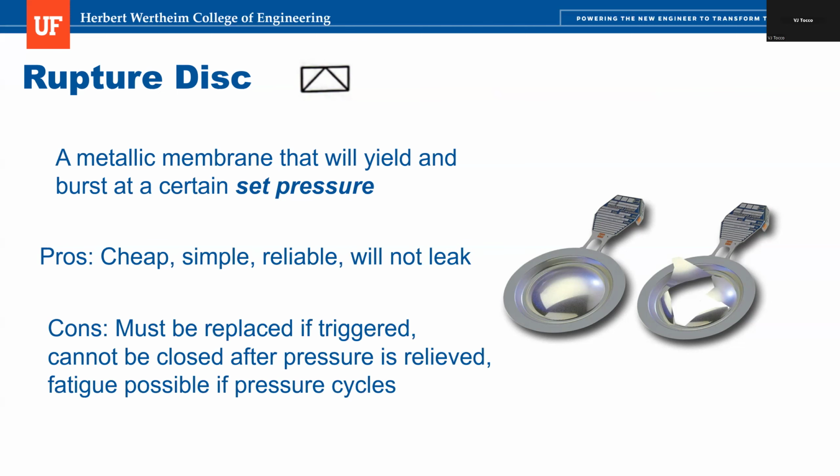Obviously, because it's so simple, there's no electronics, there's no controllers, there's no connections or anything. It is very reliable, meaning that if the pressure exceeds whatever the set pressure is, it'll just break and that'll be it. It's also relatively cheap because of the lack of the components, and very simple as well.